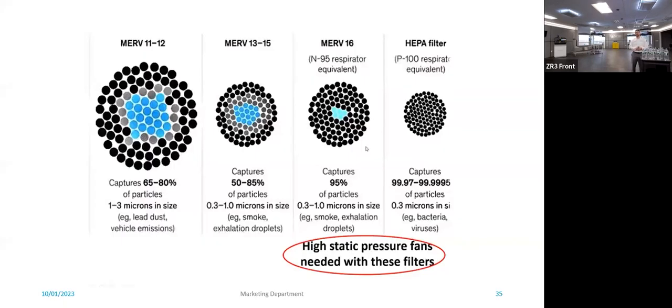So let's talk about the mechanics of HEPA filtration. Not everybody understands. There are a lot of people out there that think, and there's actually an article written from a company that provides floor-mounted systems, or actually, I think it was an ionizer company, that said HEPA filters don't filter out the coronavirus. It stops at 0.3 micron. It can't filter lower than that. That is not true. HEPA filters actually become more efficient the smaller, after 0.3 microns, so 0.3 and below, and then above, they become more efficient. 0.3 micron is the point at which the HEPA filter itself is certified.